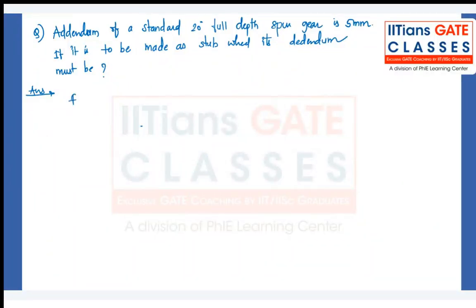For stub tooth, remember, addendum is 0.8 module and dedendum is equal to 1 module. Okay, this is something new. Write it down.